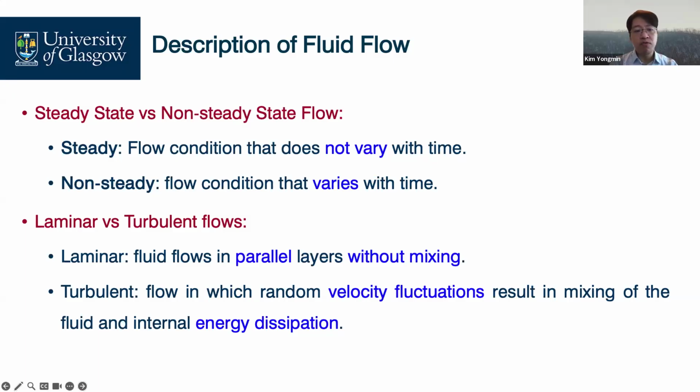And then, based on fluid mechanics knowledge, water flow can be classified into laminar and turbulent flow. But the velocity of seepage flow in most soils is too small, so the flow can be considered as a laminar flow state. It means the fluid flows in parallel layers without any mixing. It's just water flowing through the channel, which is the void.